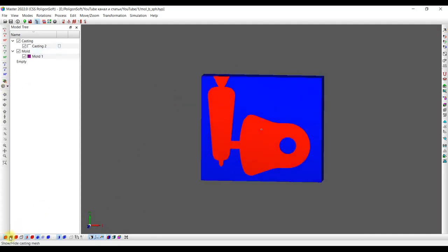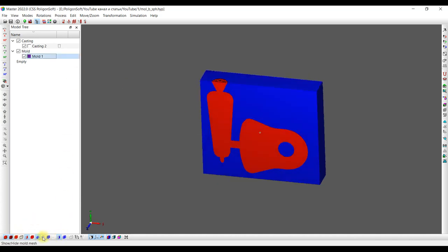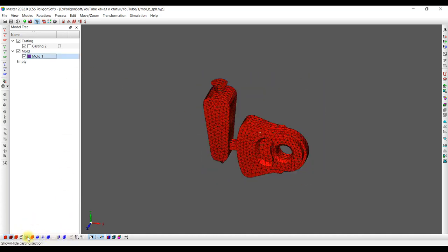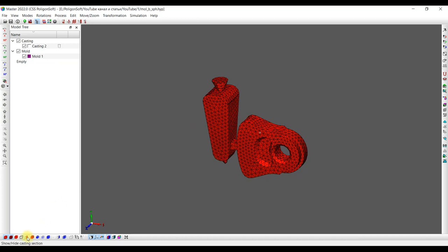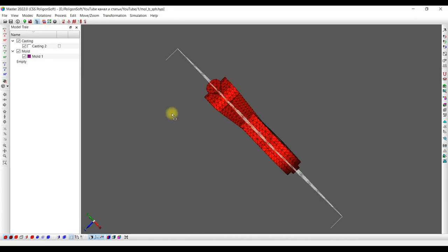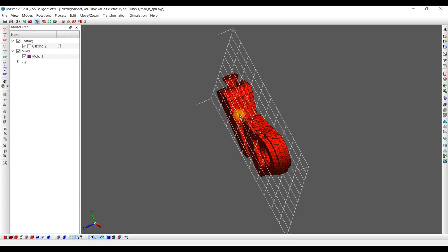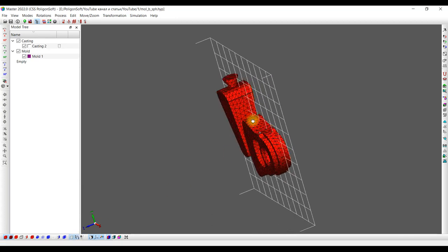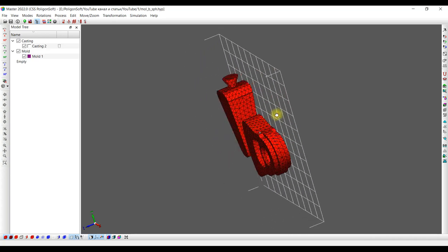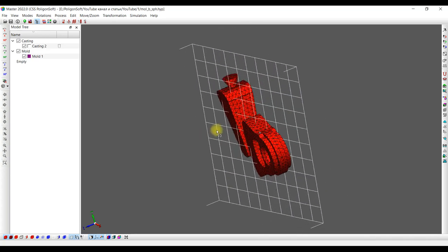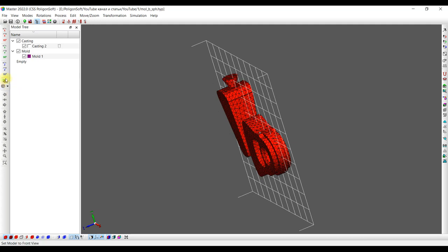Now let's talk a little bit about the display of the model. We can display a mesh of elements and nodes of elements. We can add a cross-section for different parts. The cross-section can be adjusted. The first button displays the section plane. The second button allows us to rotate the section plane with the left mouse button pressed. With the right mouse button pressed, we can move the plane. You can also use the same buttons to rotate along the axis that we used to rotate the model.